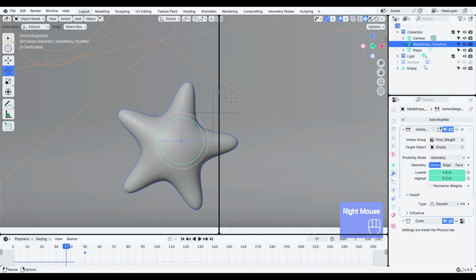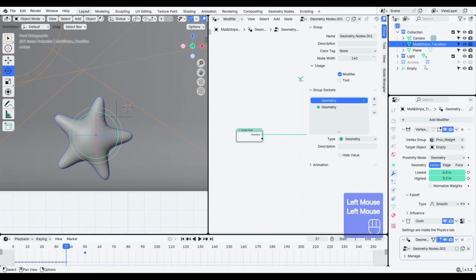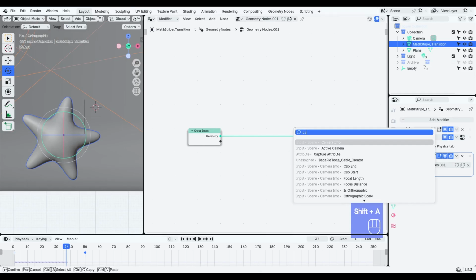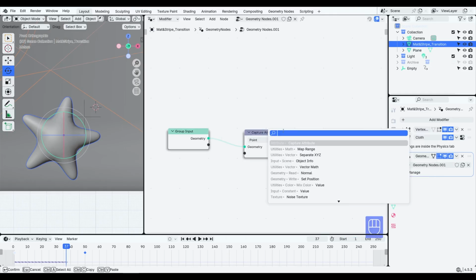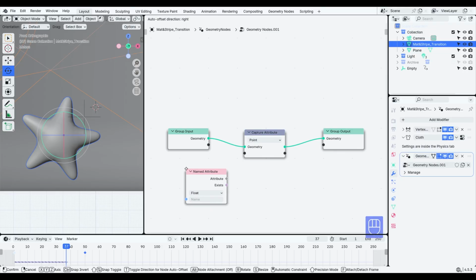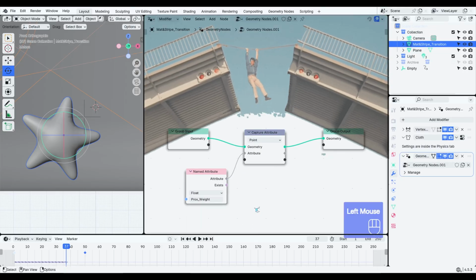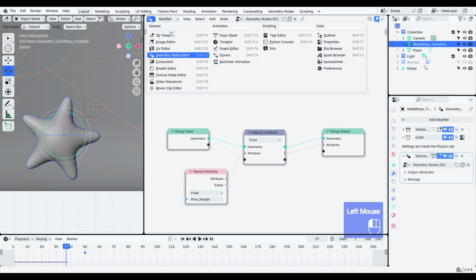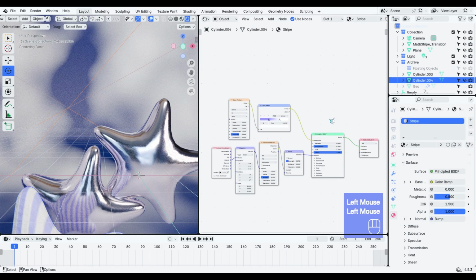Next, we can use the powerful yet simple geometry nodes to capture and store the information we've set up so far, so we can pass it over to the shader editor later. The capture attribute node is what we'll use to record values. Then, using a named attribute, we can bring that data into the material. It's basically a clean, modern bridge between geometry nodes and the shader, letting the material read our custom data, like the procedural transitions we've just built, perfectly in sync.